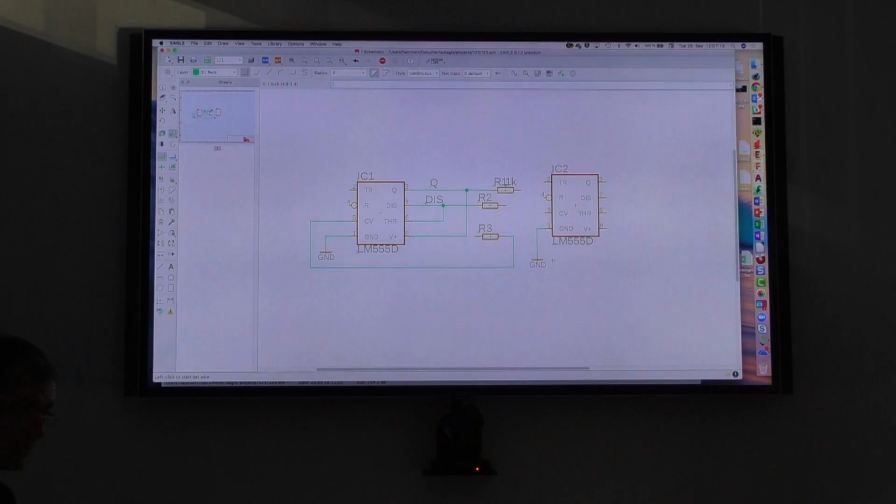Please check the name of the net. If I come from the supply pin to the power pin, I think it should be automatically named ground. If you do the other way around, or if it comes from anywhere else, it makes sense also to name it ground. If you wouldn't, it would complain and say, how pin GND is connected to N-order 25 or something like this, then I would go into the schematic and name it so that it fits together and it is no longer complaining.